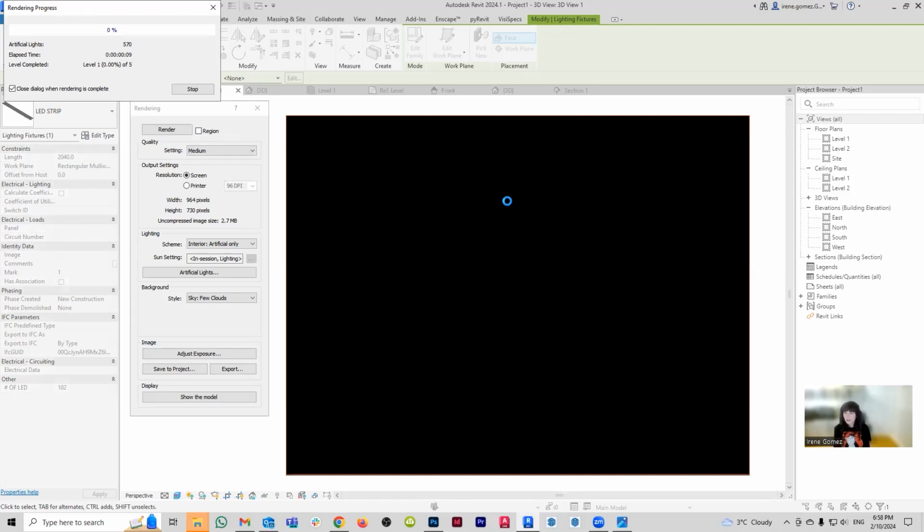You can even use translucency to give them that semi-glowy effect, and the lights are interacting really nicely with their surrounding geometry, because due to the fact that I changed it to a hemisphere instead of a full sphere, you're not getting that really ugly effect when the light cuts into the geometry next to it, and it looks really, really fake. So when you're working with lighting fixtures in Revit, it's really important that you pay attention to the light source, shape, and distribution, especially the distribution. And then obviously, what is the surrounding geometry? What is the material of the surrounding geometry?